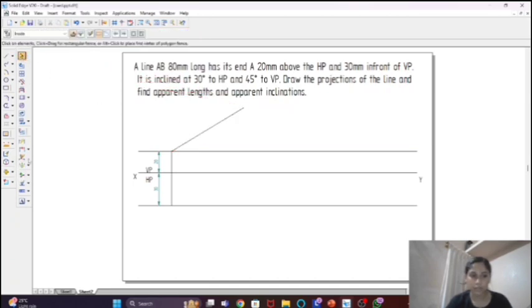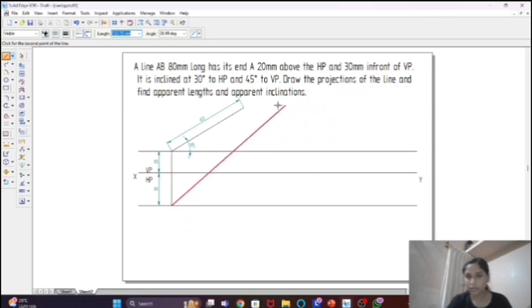So now using the angle between option you can measure the angle, and using smart dimension we can measure the length of the line. Then again you can click on the line option, move the cursor on the line towards the end. You can see an arrow, click there, and you can give 45 degrees.